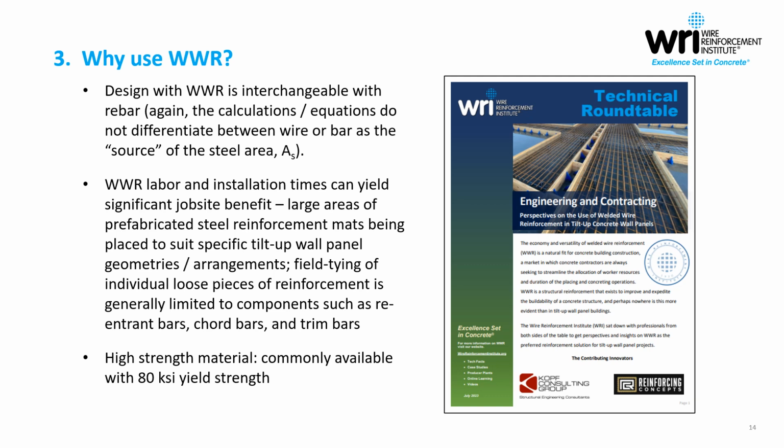In turn, the field tying of individual loose pieces of reinforcement is minimized. You still have those components like reentrant bars and chord bars, trim bars, that sort of thing, but the body of the panel largely, you're looking at 95% of a panel being handled with welded wire reinforcement. So it goes together much like a kit of parts.